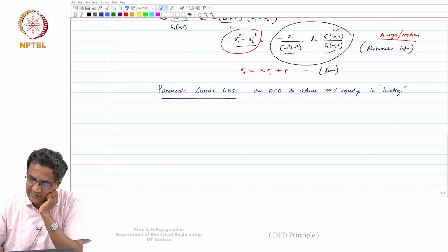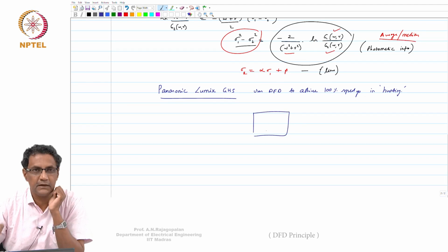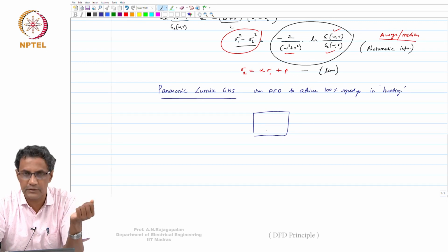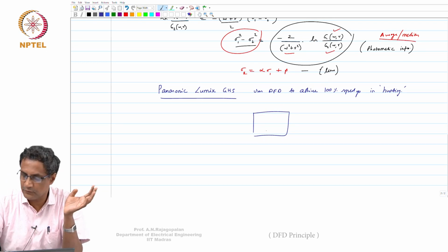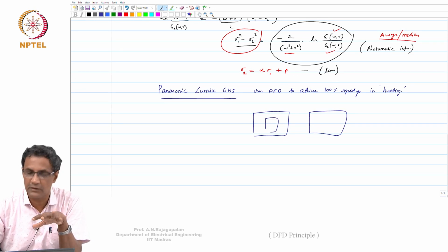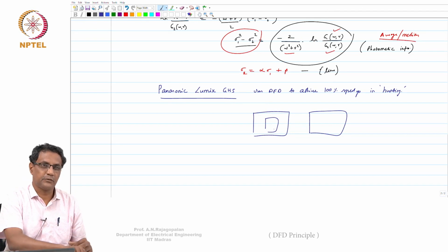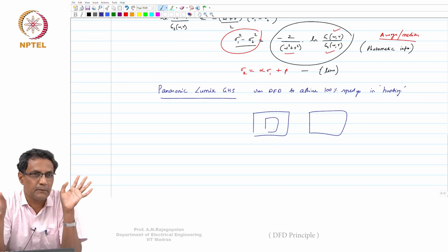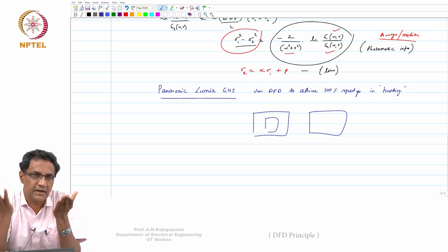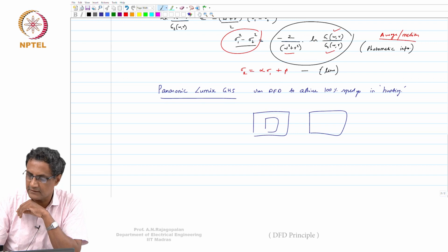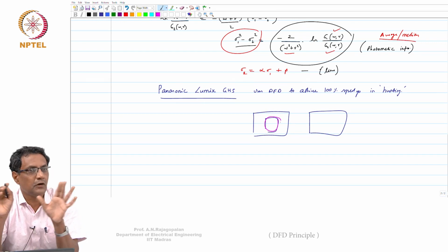Like I said, typical cameras will capture about 50 to 100 frames and look for some contrast measure, which will tell which lens setting brings the scene into focus. Instead of working on that many images, they simply capture 2 images by changing the lens setting, and they assume that the center of the image is of probable interest to you, naturally, as I said even in the last class. They assume that the central thing is probably one flat plane. It could be wrong, it could be that something is changing very drastically there, but these are assumptions they make. So they assume that this patch has almost constant depth.